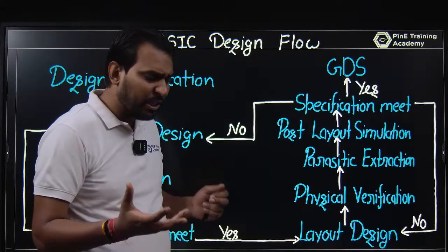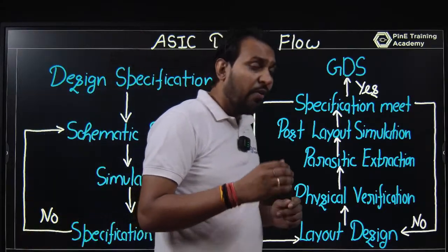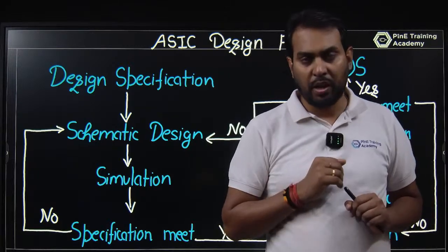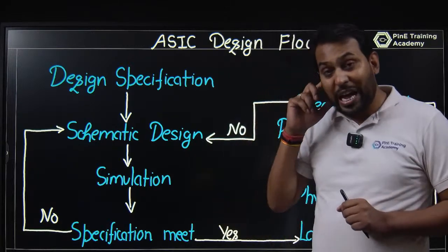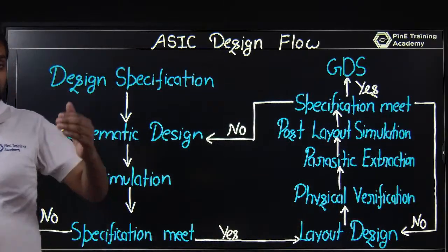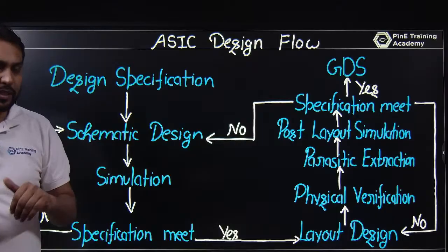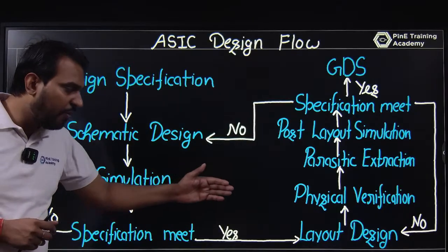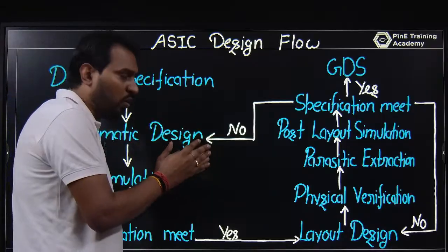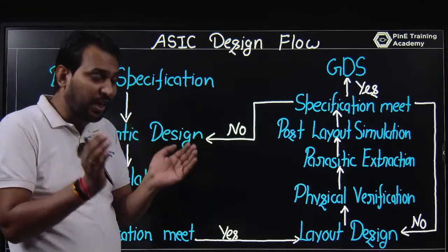Physical verification means we talk about a set of rules, like DRC and LVS. In Cadence we have Pegasus, the Pegasus Verification System, that is PVS. In PVS we have a set of rules that is designed by the library. The tech node defines this set of rules.